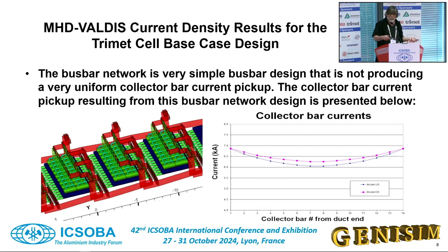If you want to compare with ANSYS, MHD-Valdez is solving the full bus bar network, so it's calculating this current pickup. The ANSYS model I'm going to use only represents the cell without the bus bar, so I need to impose the current pickup. I need to use the same current pickup, so I'm going to use the one I'm computing with MHD-Valdez.